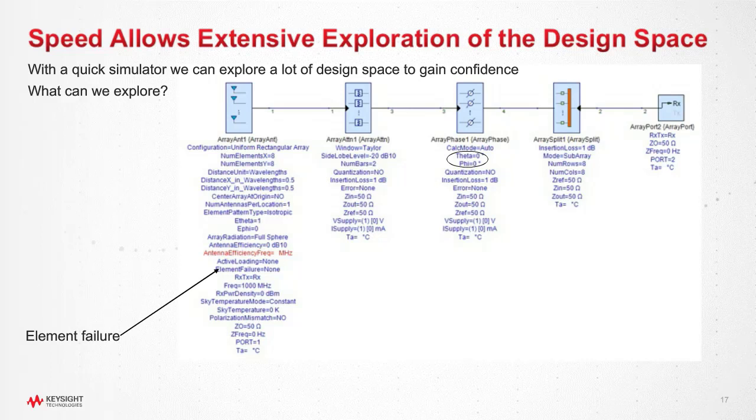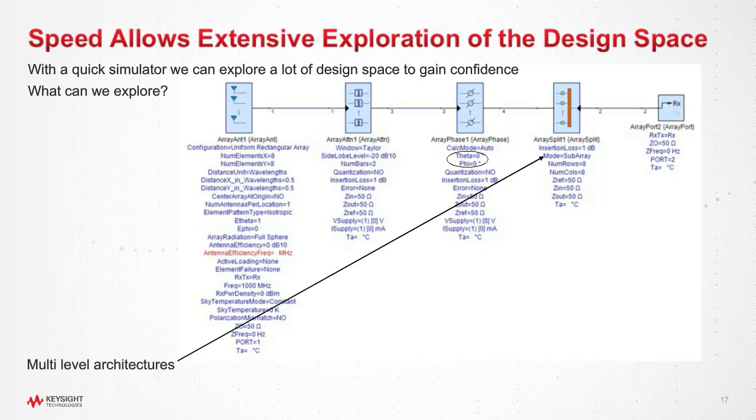If a certain number of antenna elements are failing, what will be the impact on the far field pattern, and ultimately what will be the impact on the phased array system itself. Sometimes we may have to follow both time progression and then phase progression in a design. For example, for broadband systems, we can initially do a coarse time delay method followed by a fine phase difference method so that the implementation of the phased array becomes more practical.